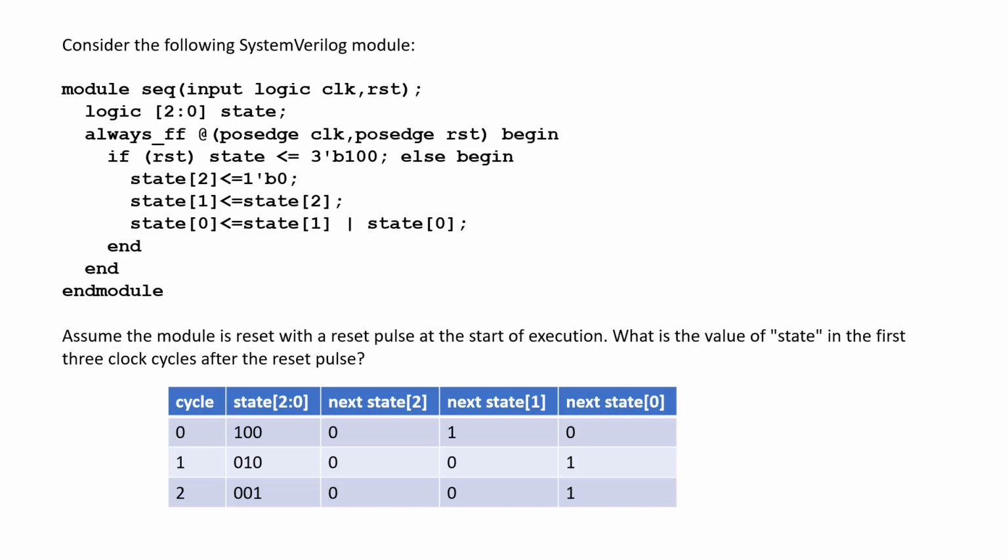It's because basically state 1 is the same as state 2, but just delayed by 1 cycle. There's an extra cycle of delay. So it takes an extra cycle for state 1 to catch up with state 2. So it takes 1 cycle to get state 2 to 0. It takes 2 cycles to get state 1 to 0, at which point they will always be 0 forever until the next time you reset. And then state 0 will basically just be 1, because I guess starting from cycle 1, it'll go to 1 and stay there, because it will just be whatever the previous value of state 0 was, right, which is 1. Make sense?